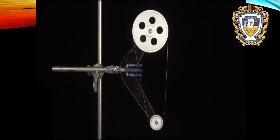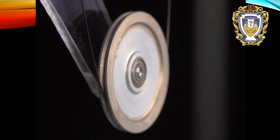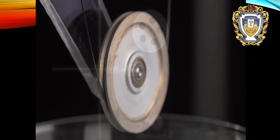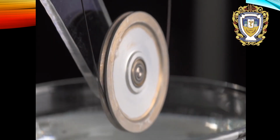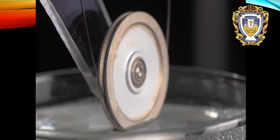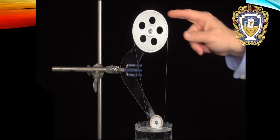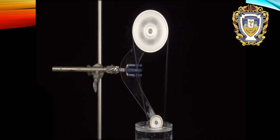There are some clever uses for nitinol. For example, this device has fascinated me since childhood. It's a type of engine. Its construction is very simple, a large and small wheel, each grooved on their side, with a loop of nitinol wire that runs through the grooves and connects them. To make it run, I just contact the lower edge of the small bottom wheel with water, which I've heated again to 75 degrees Celsius. Then spin the top wheel a bit, and the device then runs on its own.